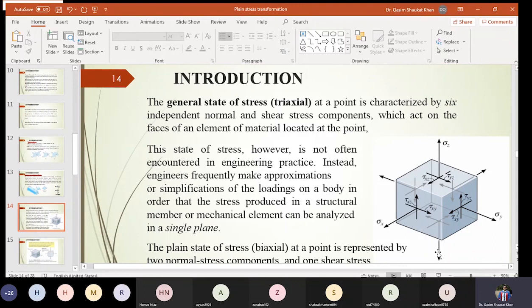So now just come to this point. There are six faces. On six faces, each face is complementary to one, so six faces are reduced to three faces. Then on the three faces, at each face you have one normal stress and two shear stresses.